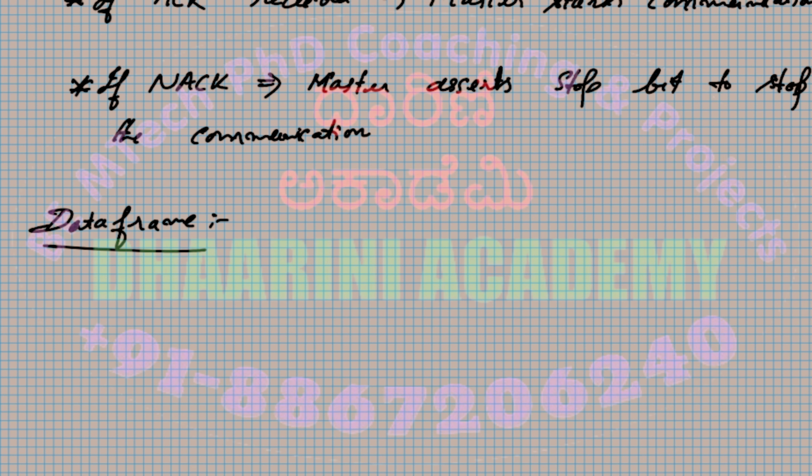That says the start of communication, followed by the 7-bit address, which contains the 3-bit address of the particular device, A2, A1, A0, right? Followed by that, you have the read or write bit, saying whether you want to read or write. And after that, you have the acknowledgement or no acknowledgement.